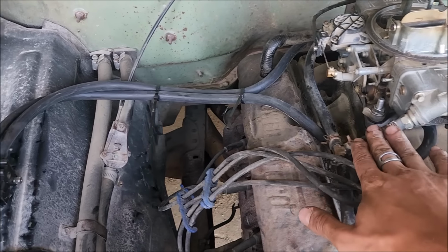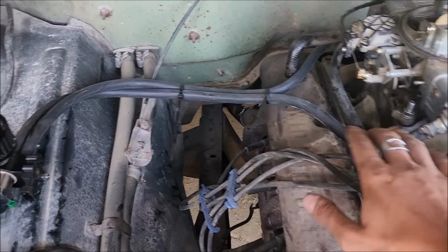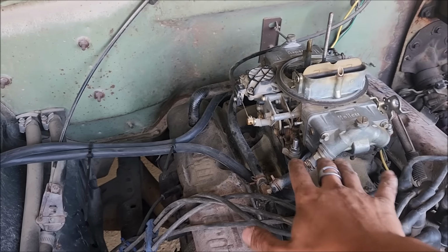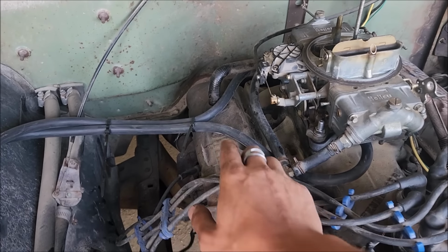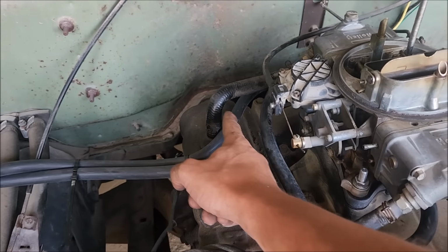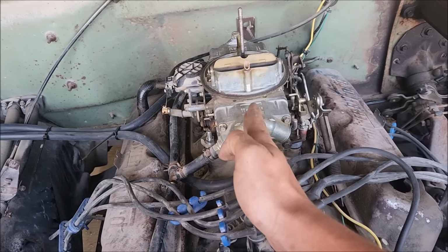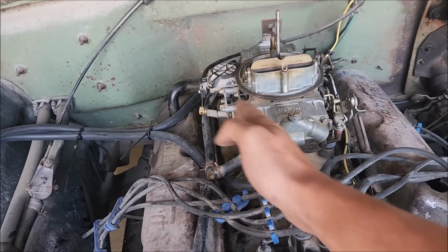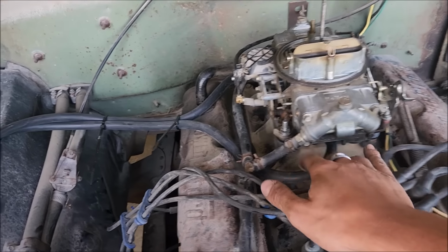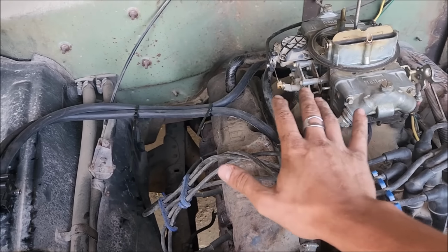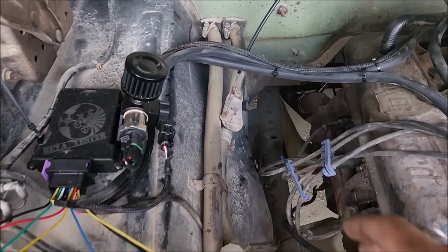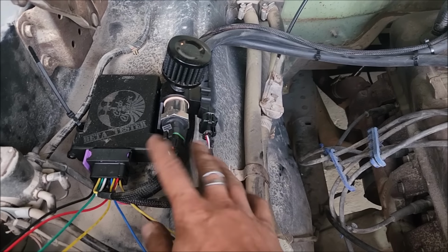Now, if you didn't have the spacer, again, you could tie the MAP sensor to the brake booster, somewhere on the manifold. It doesn't have to be a centralized port. But again, you don't want to tee into the PCV valve and you don't want to tee anything off of your Carb Cheater main valve. Both of these items need to be on a centralized, dedicated port where they're even to both throttle bores and there's nothing tied into them. Again, that's extremely important.